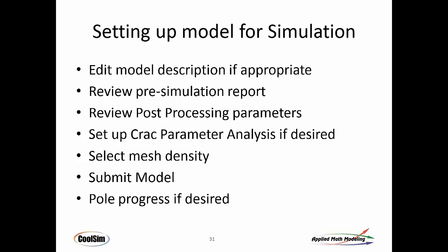Presimulation report is important. This is a CoolSim feature, but in any kind of case, you'd want to always review your input parameters and make sure they're set up correctly. So I encourage people to do that. It saves time because oftentimes you'll make a mistake on keystroke entry or things are out of whack. Presimulation report shows you that and kind of gives you a feel for what is being fed to the cluster.